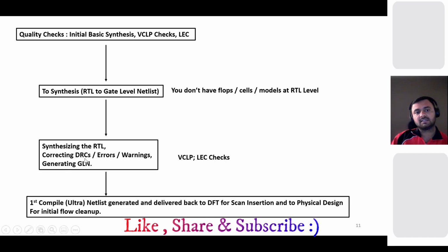There they will also correct many DRCs, design rule checks. There will be some linking errors and some warnings, so they have to correct everything, and then they will generate the gate level netlist. But again, they will do the VCLP and LEC checks, because before generating the gate level netlist, they must make sure that between your DFT inserted RTL and the gate level netlist, the functionality should not change. They will check all the power formats, all the LEC, everything. Then they will release the first compile netlist, which is also called the ultra netlist, and it will be delivered back to the DFT team.